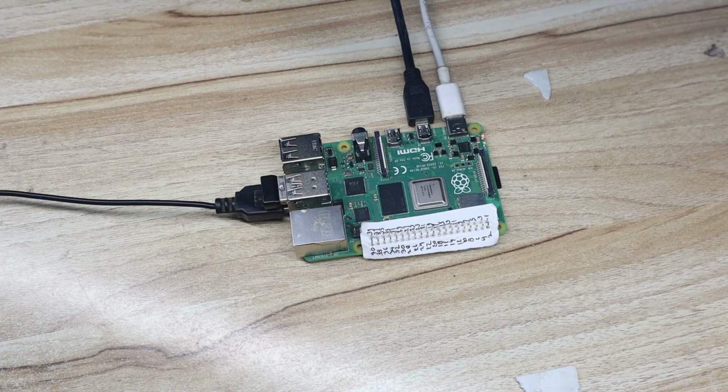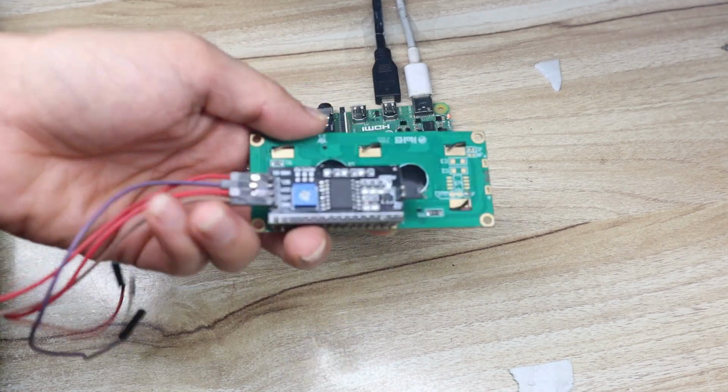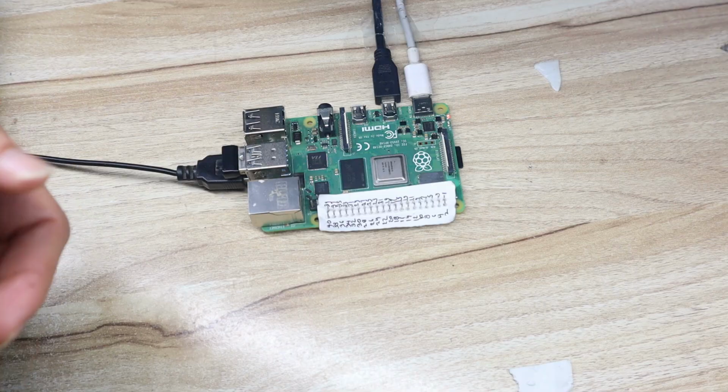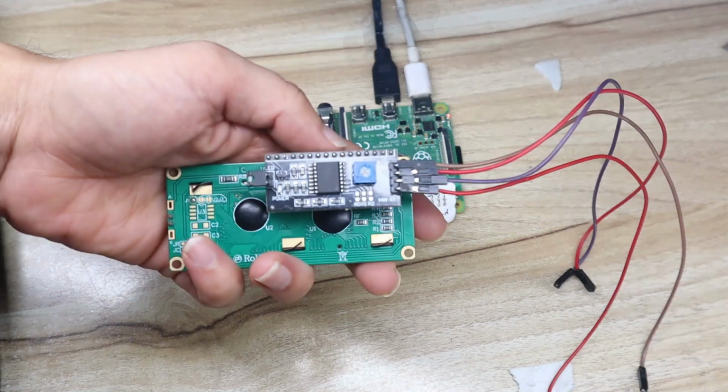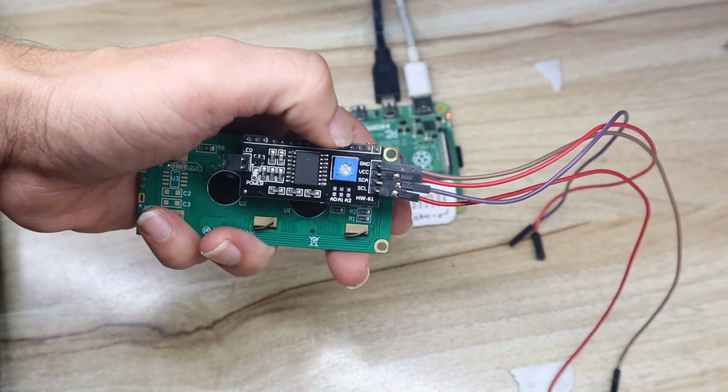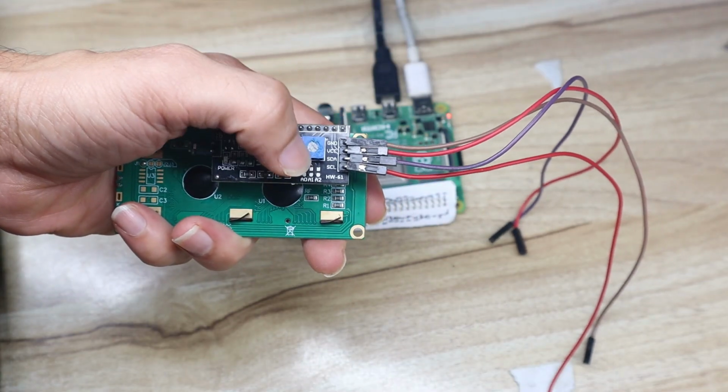So initially we did the Raspberry Pi screen start, and now the next part is the connection of our hardware. The hardware connection, I told you, is given in the program. Once you open my final code, I will show you the program part also. At the start of that code you will find the connection, then you just have to connect the wires as per that program. Okay, so let's connect one by one. First connect the I2C LCD. Okay, now the next hardware is our I2C module. The I2C LCD module is a very easy and simple connection. It just has 4 wires: VCC, ground, SDA and SCL.